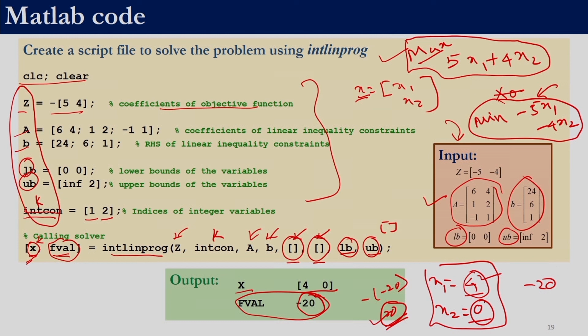So over here we did not use exit flag, right? What we could have done is, instead of just stopping with x comma fval, we could have given x comma fval comma exit flag equal to this right hand side as such, right? So in this case it would have given us the value of x, the value of fval, and also a number with which we can find out the reason for termination of the algorithm.